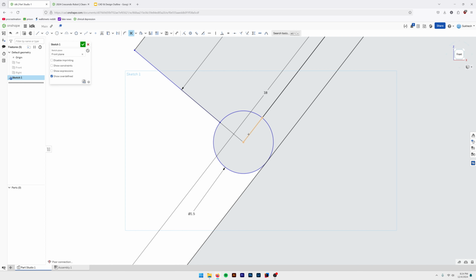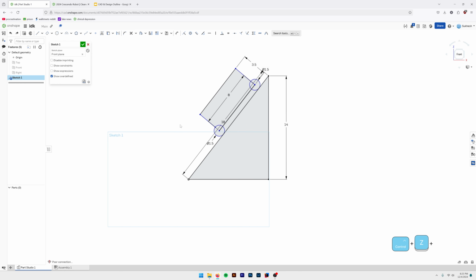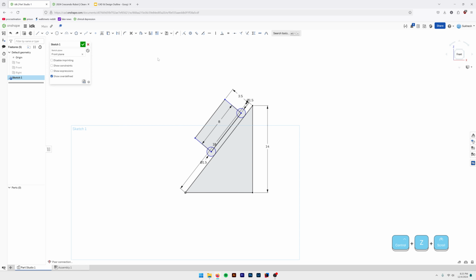So this is going till here because it touches something over here, so that's a line segment, and then you can just delete it. So you can either click on it or you can drag like that and delete it, like Fruit Ninja, where you can just drag and swipe and delete stuff like this. It gets kind of fun. So that's trim for you.